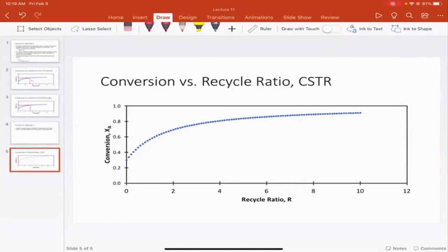It also adds infrastructure into our system, which can increase cost and complexity and all that kind of stuff, right? Because we had to add a separator, we had to add a mixer. If it's a liquid, there's definitely going to be new pumps everywhere and new temperature controllers and all that stuff. So you do add some complexity, and offsetting the cost of all of that with how much you sell the product for, how important size is in your facility, as well as the initial capital cost for a smaller versus a bigger reactor, all those would come into play in the future.